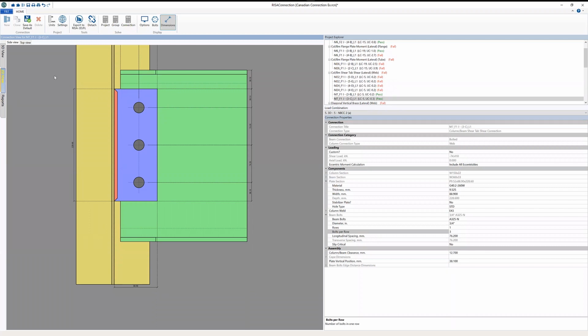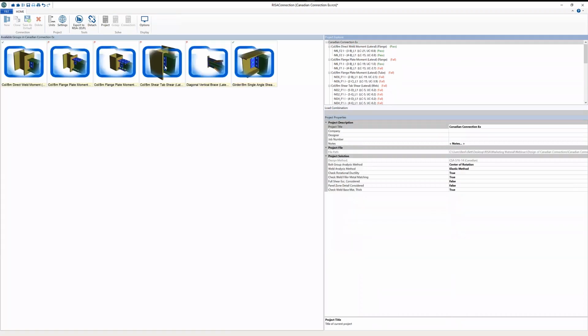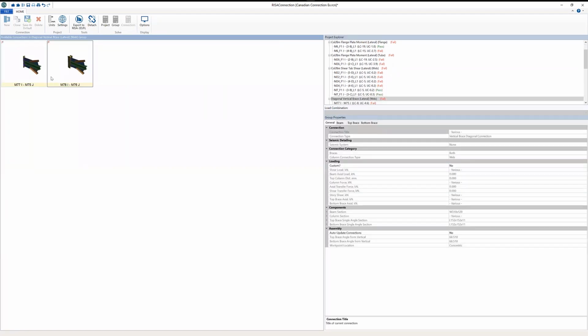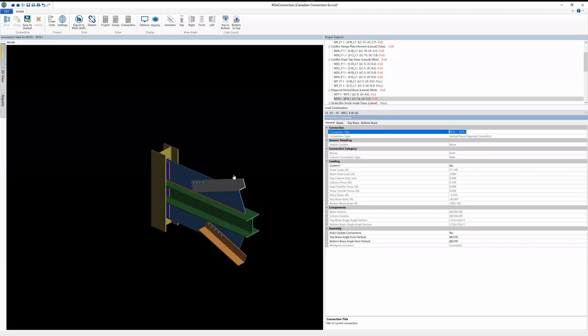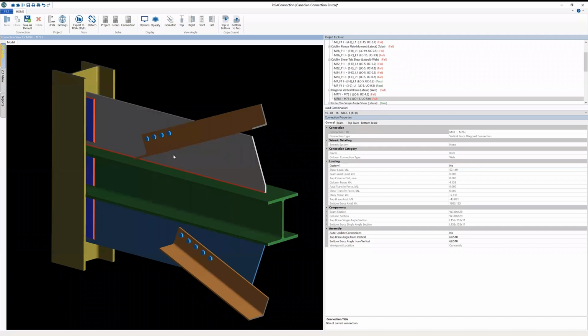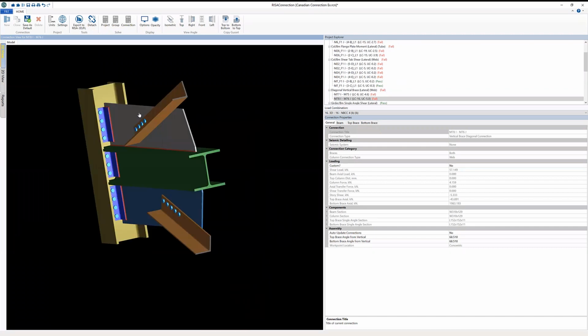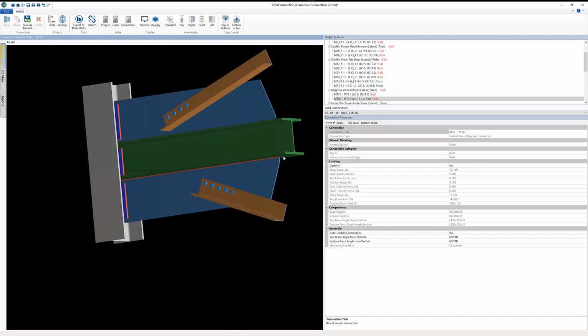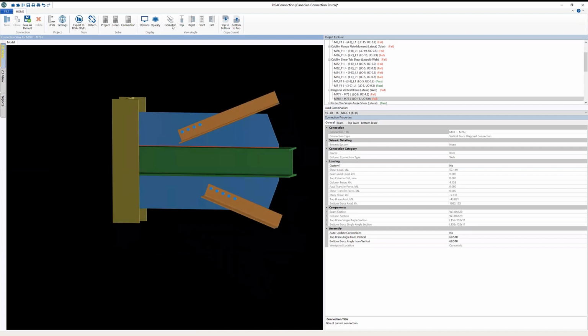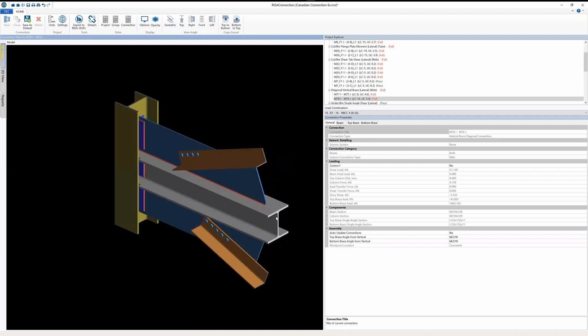Okay, let's go ahead and look at the brace connection, because those seem to be the most fun. They've got the most going on. So we're going to look at this second one here. This particular brace connection is a weak axis connection. It's framed into the weak axis of a column here. So we've got plates welded to the gusset here.